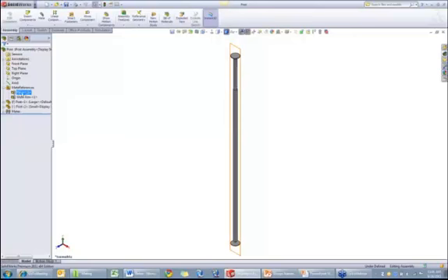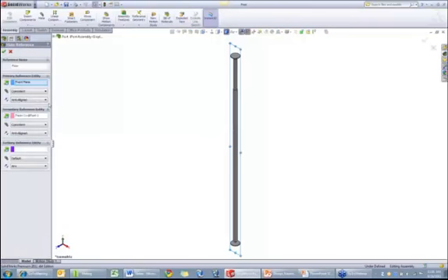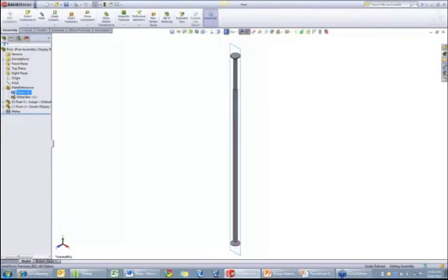I have this floor reference, first of all, that is using planes or faces as a primary or tertiary reference entity. And this is more of an advanced mate reference, because you'll notice that the name of that mate reference is going to match the name of the base that I have inside of that main assembly. So if any of your mate references are named the same, it's going to try to use those together when you drag and drop that component into your assembly document. So more on that in just a minute.